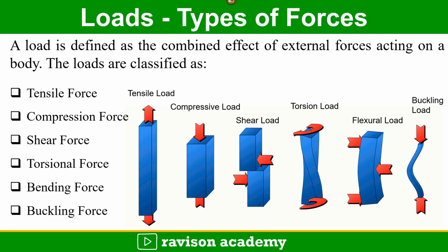Coming to the load, load is defined as the combined effect of external forces acting on the body. The different types of loads are tensile load, compressive load, shear load, torsion load, flexural load and buckling load. In the tensile load, a stretching force is applied along the axis of the object. Similarly, in the compressive load, a pushing force is applied.